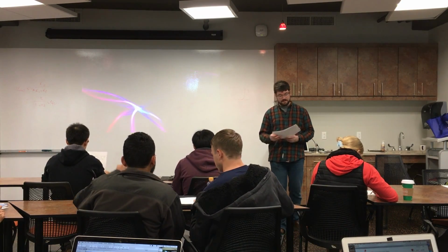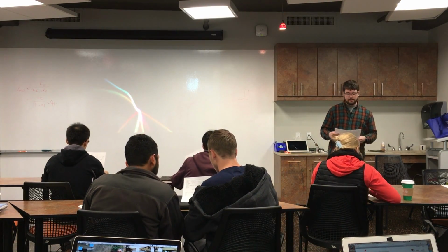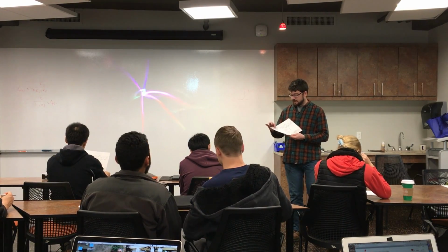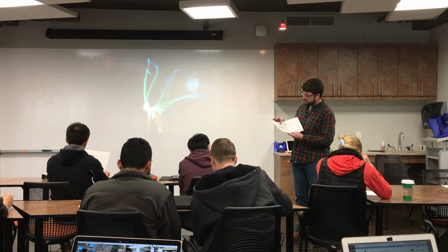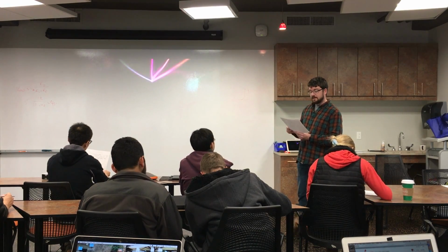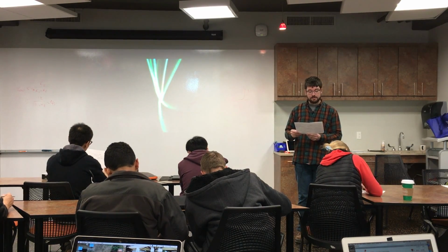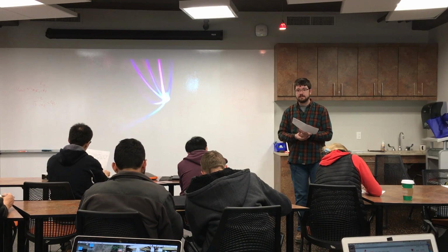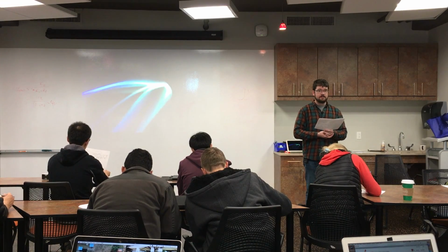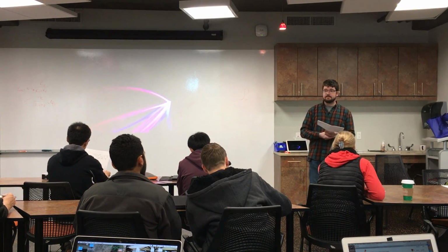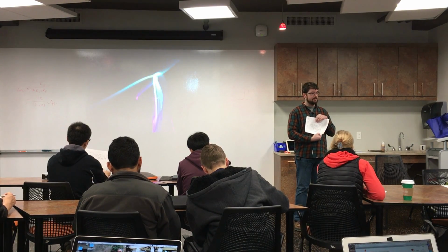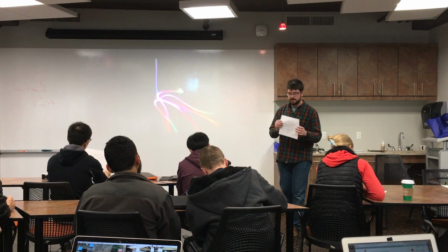Okay, so now onto the one that everybody did. That's actually a little bit trickier. So in the top left corner, you have an OP177, and you've got this front panel set point coming into the non-inverting input, and then you have feedback on the inverting input. Okay, so what are we doing there? So that's a unity gain inverting amplifier. So it's going to take whatever voltage is here, invert it, and spit it out there. It's like a voltage follower, but with a -1 multiplier.